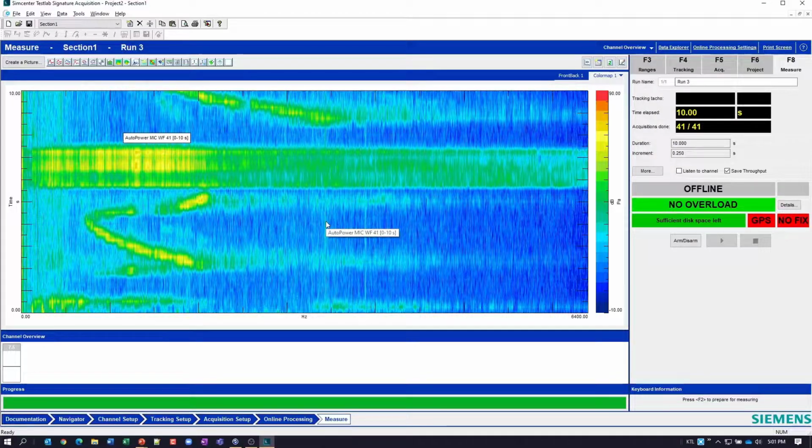Real straightforward, simple. If I had an engine RPM or a rotating speed or a miles per hour speed channel that I wanted to add, very simple to add that. Just instead of tracked on time, I would select tracked on a channel in that tracking setup page. Okay?